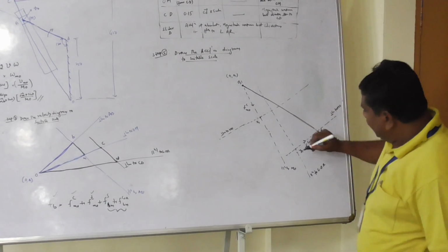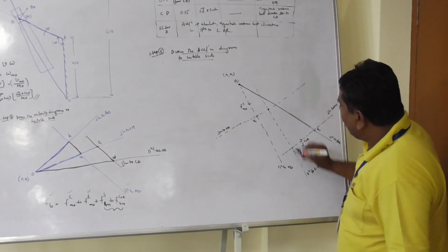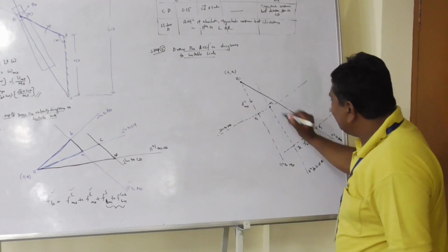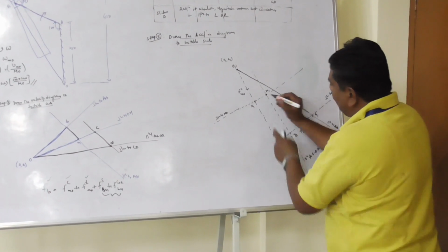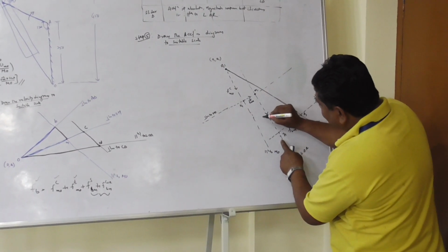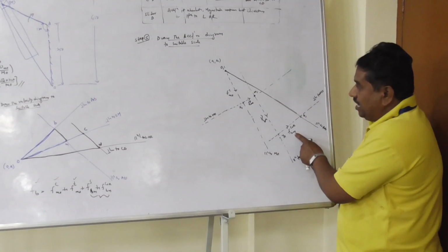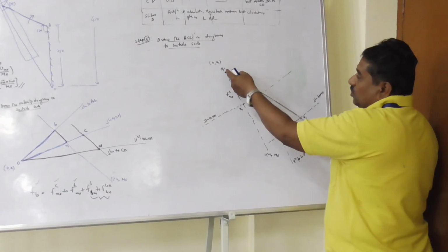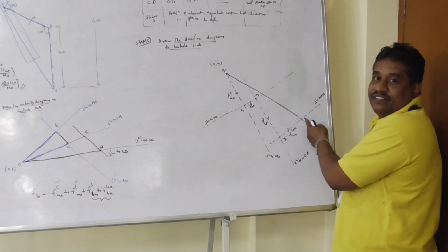Parallel to line of reciprocation. This parallel line and this perpendicular line intersect at this point. Here I am going to get the point as M1. Now centripetal X1 to M1, tangential component of MO, M1 to Y1, sliding component of BM, Y1 to B1, Coriolis component of BM. Centripetal, tangential, sliding and Coriolis, the total vector summation of these 4 quantities will be total acceleration of B.